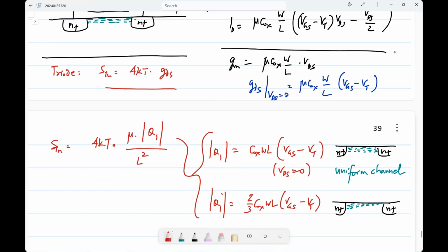So you have to see where the errors come from. For hand calculation, even if it is not VDS equal to 0, not deep saturation, but you use one of these formulas, you will get an answer that is reasonable. After that you can go and calculate it. So there is no point calculating this very precisely when there are so many other sources of error.